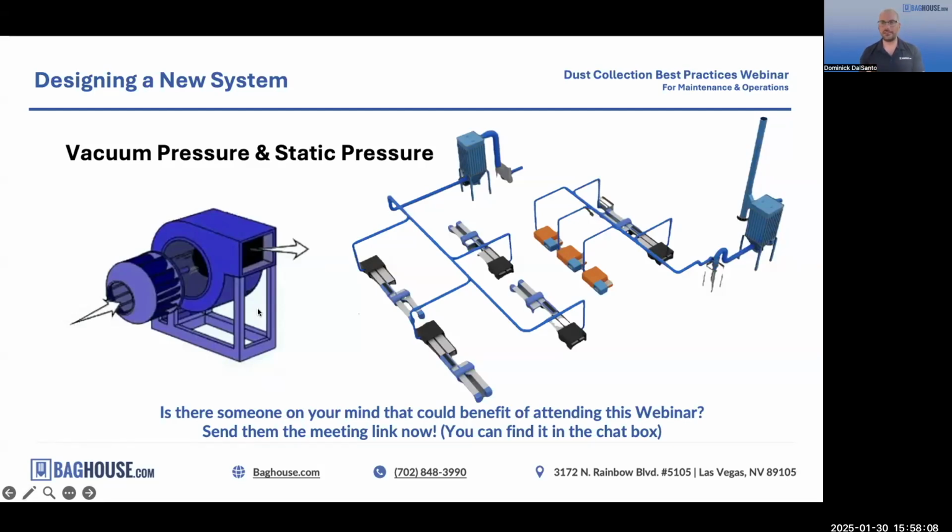So generally speaking, the baghouse is the only thing that changes the resistance. Whether the filters are dirty or clean, the resistance it makes goes up and down. The ductwork pretty much stays the same no matter what you do, unless you change how much air is going through by a lot. So that's why we monitor the differential pressure a lot.